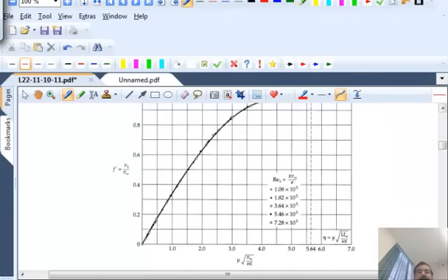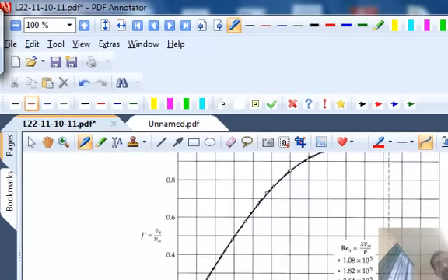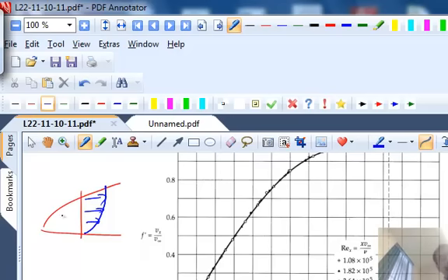Now, this is a proof of the velocity measurement inside the boundary layer. So what they have done here is measure this curve at various locations. And remember, this is a self-similar solution because we have used similarity transformation. So if I have this curve, I should be able to stretch that at a certain distance away from there to produce this curve also.